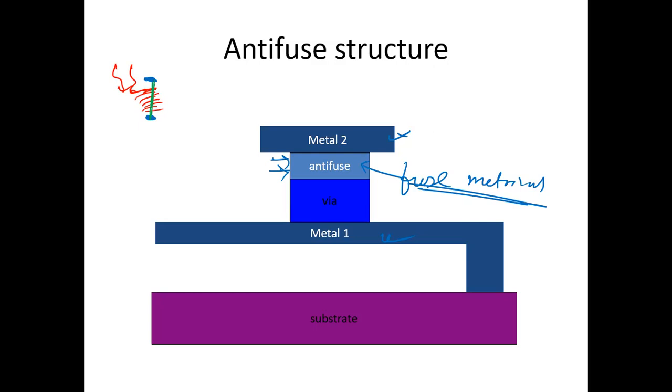But whenever you face a question that is written, you just give an example of antifuse type of FPGA, that time you just take an example as a circuit, like for example AND or whatever, isn't it? And that circuit you make through the multiplexer base. So if the question is associated with SRAM base, that time you give the design like that lookup table base, and if the design uses antifuse, that means you are using multiplexer base. Clear?